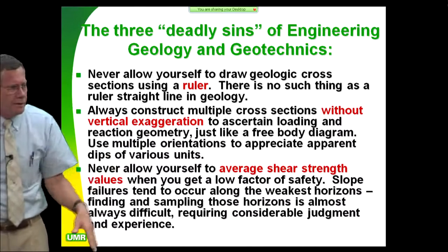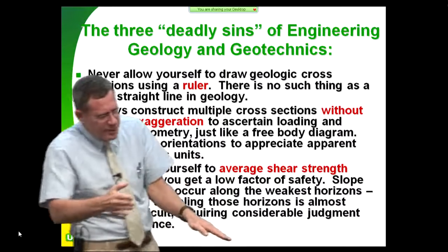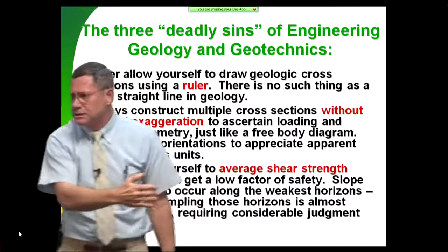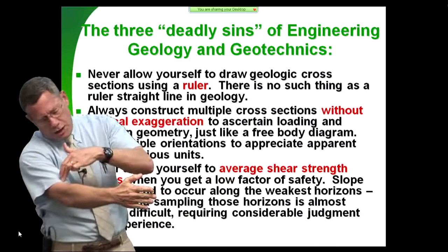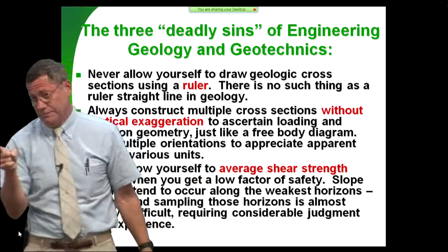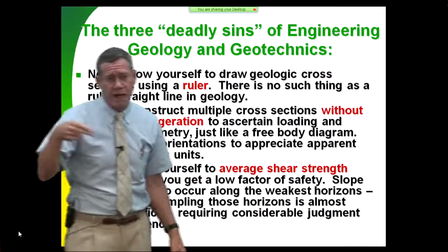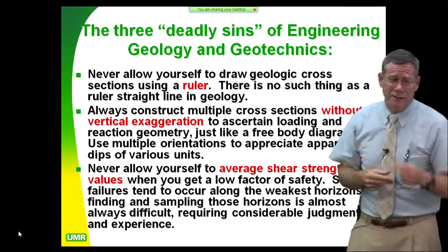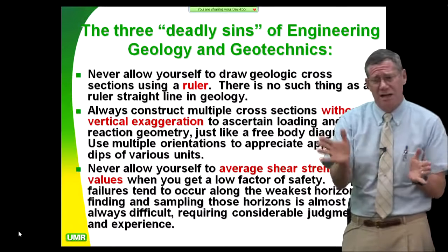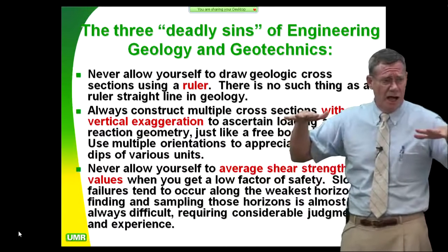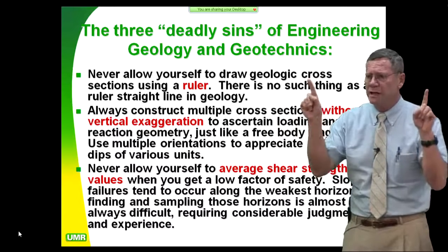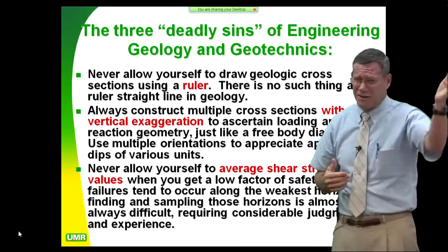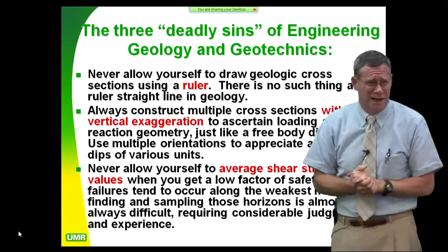Go out and look at a map. Channels going like this, they build levees semi-parallel to the sinuosity of the channel. Those old channels are cutting under the levees at acute angles. And when you do the seepage analysis along the line of seepage, you're going to get a different answer. And that's a big problem that we have to get over in the 21st century. I had them do this out in Sacramento, and 75% of the seepage analyses they did at the design height failed. Just doing it that way instead of the 90 degrees to the axis way, which dates back to the 1930s. Come on, kids, we've got to learn a few things since the 1930s.